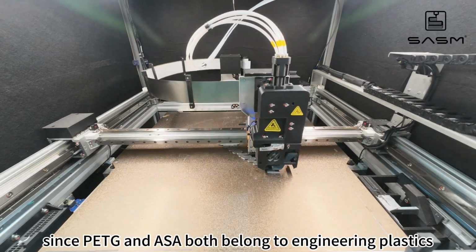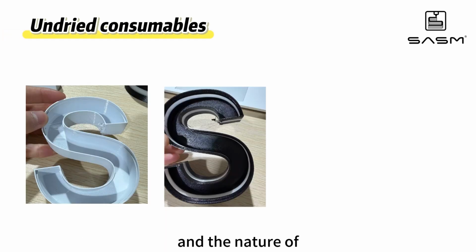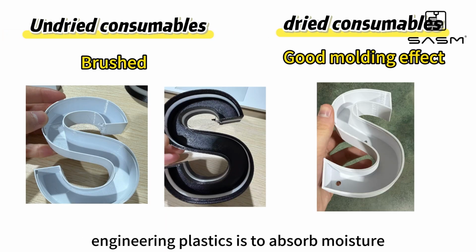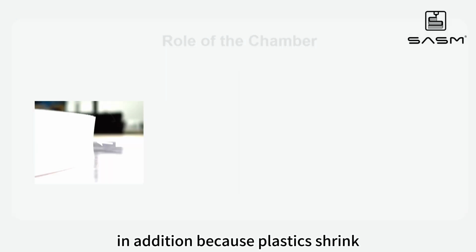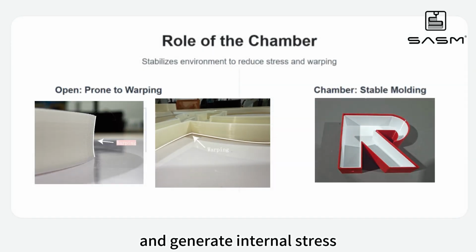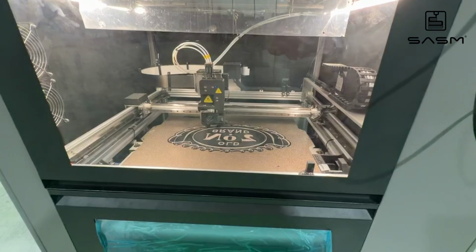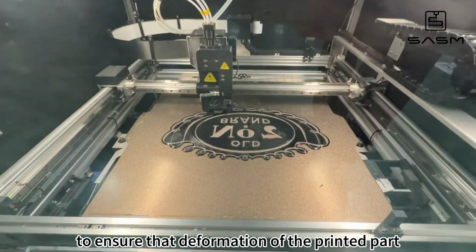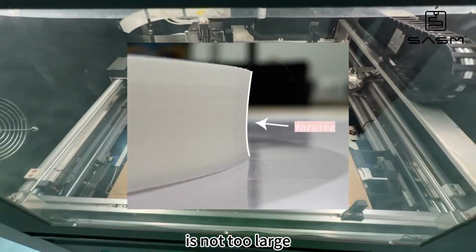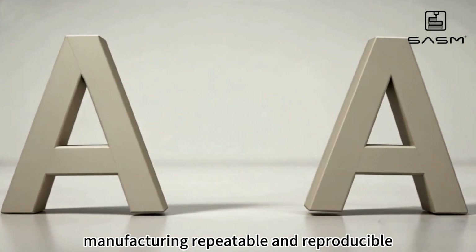Since PETG and ASA both belong to engineering plastics, and the nature of engineering plastics is to absorb moisture, dehumidification is required before printing and also during printing. In addition, because plastics shrink and generate internal stress during high and low temperature cycling in the forming process, a heated chamber is required during printing to ensure that deformation of the printed part is not too large, and also to make production and signage manufacturing repeatable and reproducible.